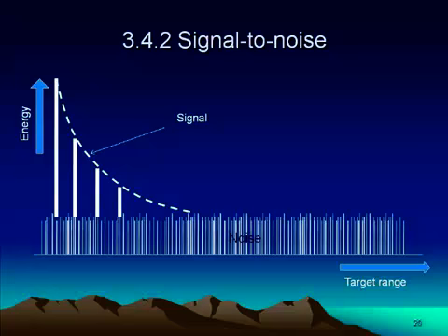That means at the third point of the graph, you can see the target can be detected properly. So that is the farthest point from which if the target sends any echo, it will be detected by the receiver. That distance can be called the unambiguous range of the radar system.